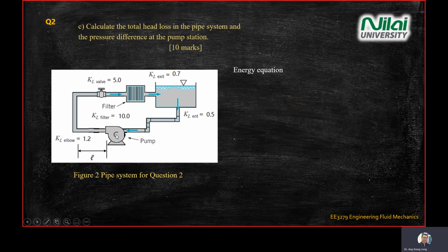So you always start with the energy equation. Because you focus on this section, on the pump section, your Z is not changing, it is the same elevation. Velocity is constant inside the pipe as mentioned, right? So V1 equal to V2. You can use section 1, section 2 here, or section 1, section 2 here also, and then you add up all the head loss, right?